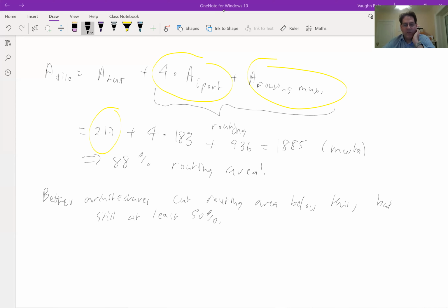And there are some research works where people have looked at truly three-dimensional FPGAs where they stack multiple dice and use through silicon vias. But there are a lot of manufacturability and practicality issues. So I guess the short answer is it's still 2D with a bit beyond 2D enabled by interposers. But truly three-dimensional structures have been proposed but haven't really been manufactured. Okay, thanks. You're welcome.